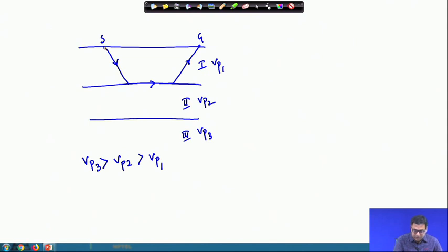Here there is a direct ray. Similarly, I am doing the derivation for the two layer system only. This is the first layer and this is the second layer. So there is a direct ray, Td, which is xn divided by VP1. So this is the xn.